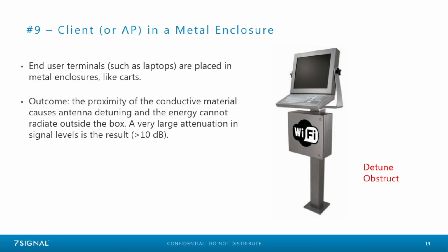Yeah. I don't see this a lot. I used to see it more, I think, but it's the painted antenna, and usually you're okay as long as it's a water-based paint and it doesn't have any metallic elements in it. But there are some paints that are somewhat conductive and will affect the resonant frequency of the antenna. If you have to paint the antenna, then at least get one and do some tests, painted versus unpainted, and make sure that it's not affecting the pattern or the resonant frequency of the antenna.